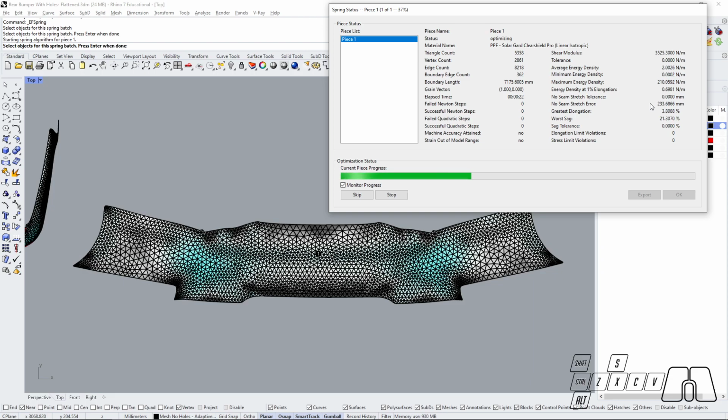The reason why I was trying to not get as many polygons as I could is because this optimizer will work better if I don't have a very large amount of polygons in my mesh. So the lower the better, as long as I'm still keeping up with the fidelity of the whole mesh.